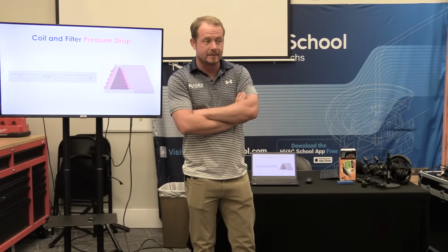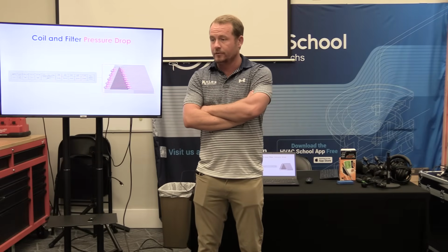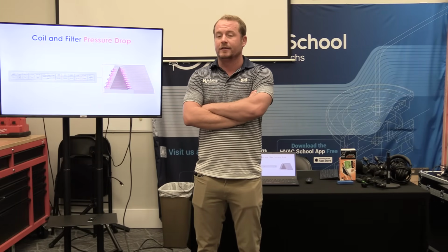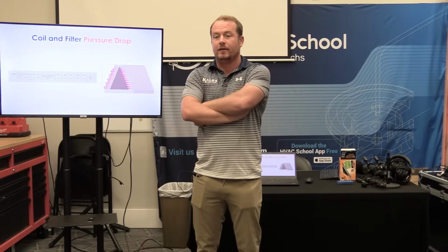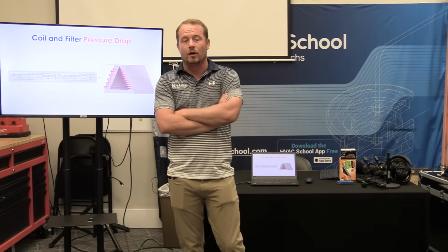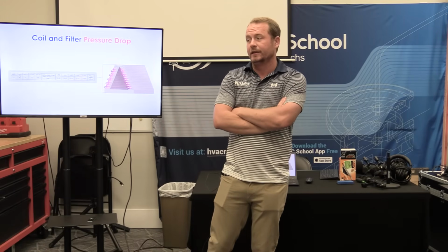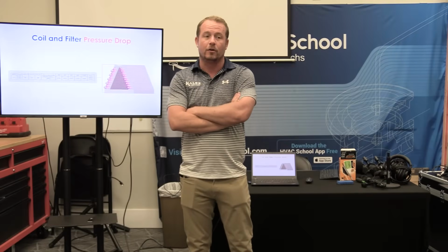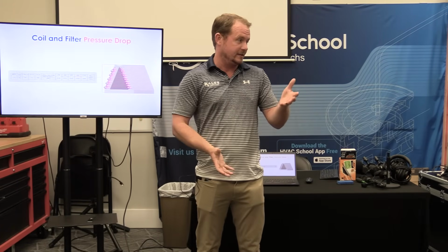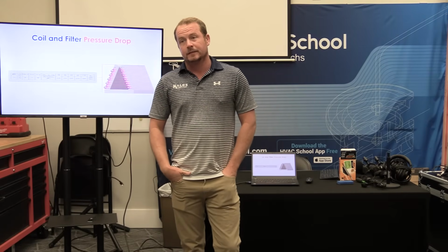So the goal is measuring static pressure when there's a reason to do so, knowing how to do it properly, knowing the different types of tools. And again, I do want us to start using, I was actually talking about you, Aaron, I do want us to start using the TrueFlow Grid and the DG8 more often, both installers and senior service techs, because it is a really nice tool for measuring total system airflow, but also for doing things like measuring whether or not you have a room that's pressurizing, whether the return and supply is balanced, that kind of thing. Very handy.